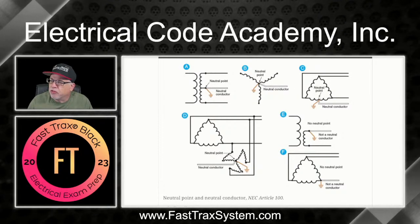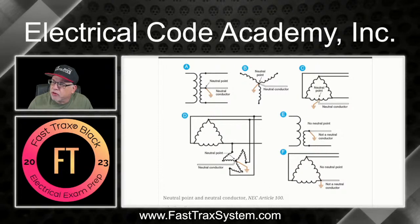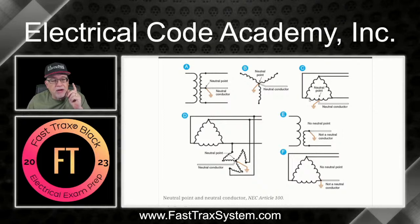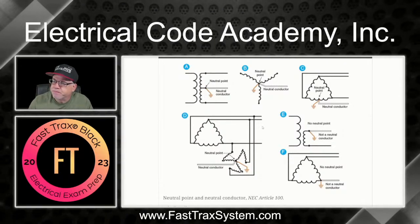Number 3, so this is an example of a 3-phase delta 4-wire system that's derived from it. And right here, here's your midpoint. And from here to here, it's going to be 240, or could be 480. And then from here to here, in this winding, if this is a 120/240, then from here to here, this would be 120. Right? So that is a neutral conductor in this configuration.